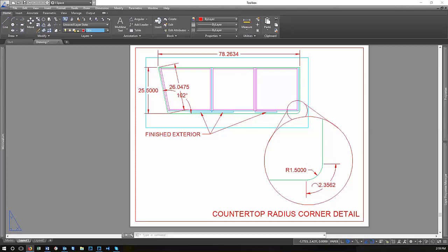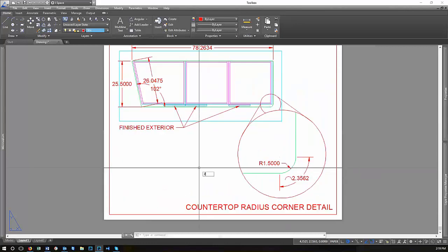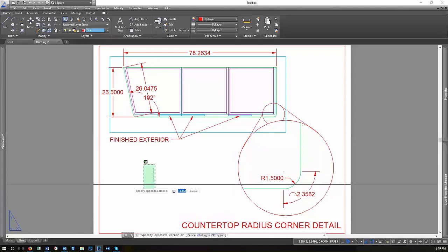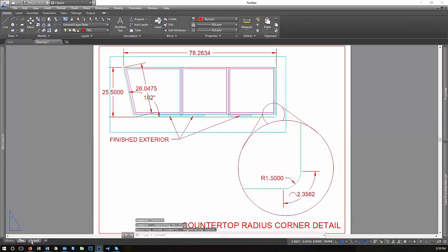Okay, so all right, moving right along to printing. So I told you we'd get back to the plotting, that plotting tab. If you go into layout, but by the way, you can double click on this and type in whatever you want to call this, and your layout tab will get renamed, so you can easily differentiate between layouts.